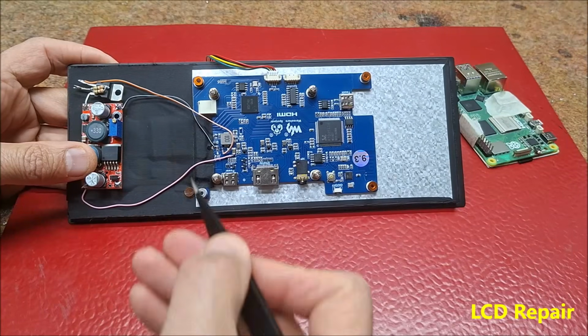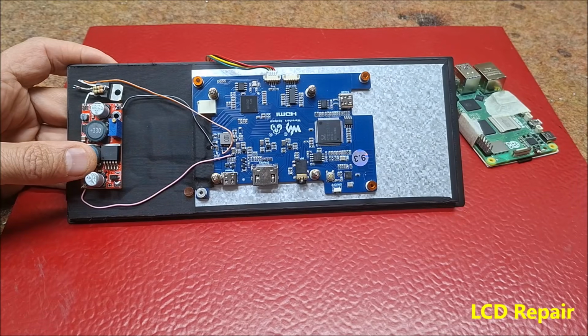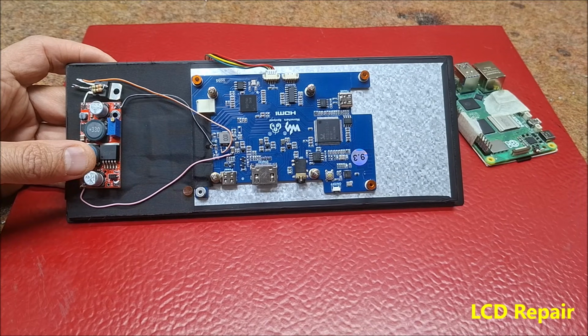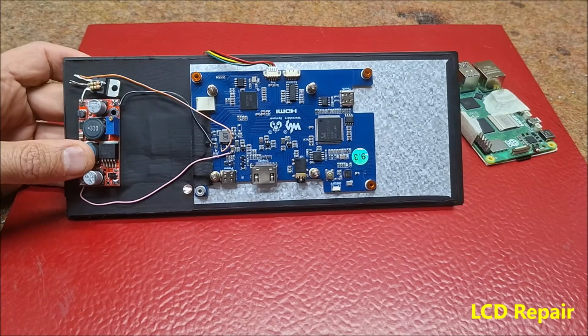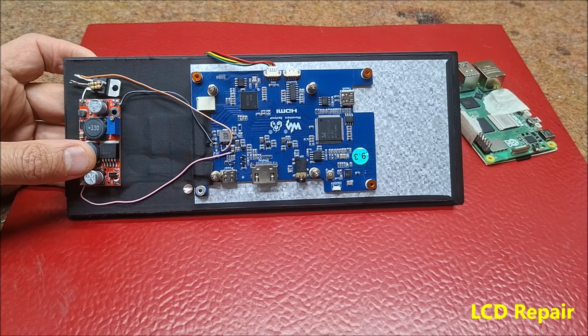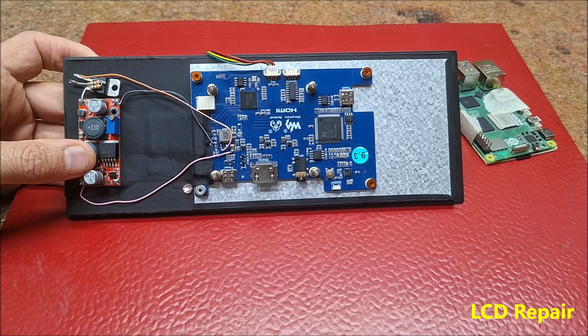So in place of the cutout of the Schottky diode here, from the boost converter circuit, I connected 12 volts with a limited current of 10 milliamps. The backlight appeared with a very weak intensity and flickering. Then I gradually increased the limited current to 60 milliamps, and I got a completely normal LED backlight on the display.